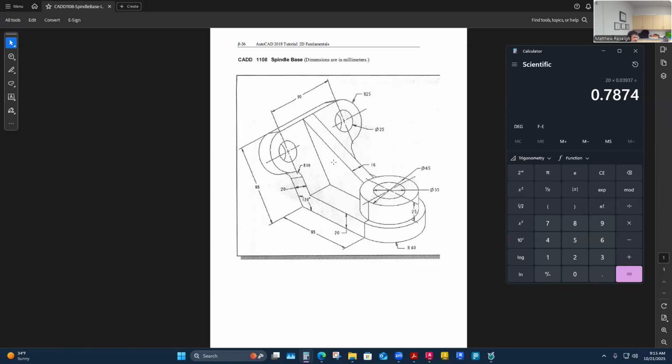And so this is a gusset, and this is how it's used a lot in manufacturing practices as a strengthening feature. Even if it was a 3D printed part, it would strengthen that part substantially to have that gusset. It just depends on the loads this is seeing. So it's definitely an engineered design, and it might be based off of previous failures.